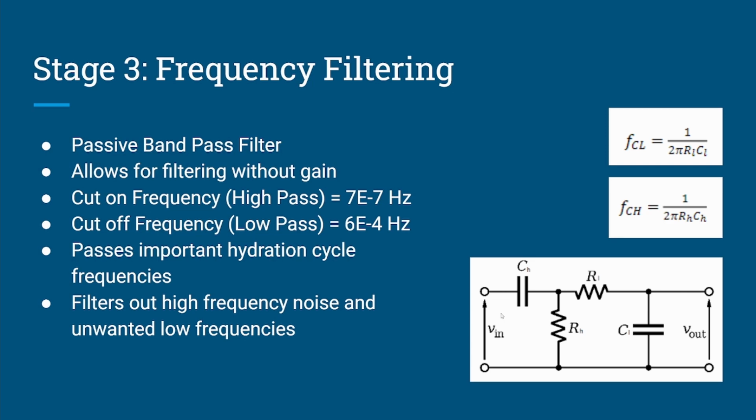The reason we decided to use a bandpass filter for this application instead of a simple low-pass filter was that with a device so small, we do not want to be wasting power amplifying and passing unusable, extremely low frequencies. This issue was resolved by the high-pass portion of the bandpass filter.